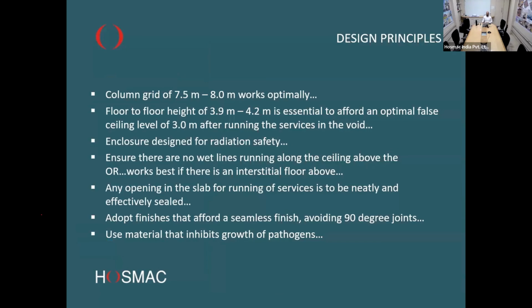What should be the floor to floor height? If you are doing a retrofit or planning afresh, you need to ensure that the floor height for the surgery suite is taken care of early on, because if you go with a conventional 10 feet, 12 feet, you're likely to end up with a false ceiling which is not very optimal. The requirement is that we should have a false ceiling at 10 feet, which is 3 meters. To achieve that false ceiling level, and to ensure that the services running above the false ceiling are adequate and optimal, we should be looking at a floor to floor height of 13 to 14 feet. In which case you will get a decently respectable false ceiling height of 3 meters or 10 feet.